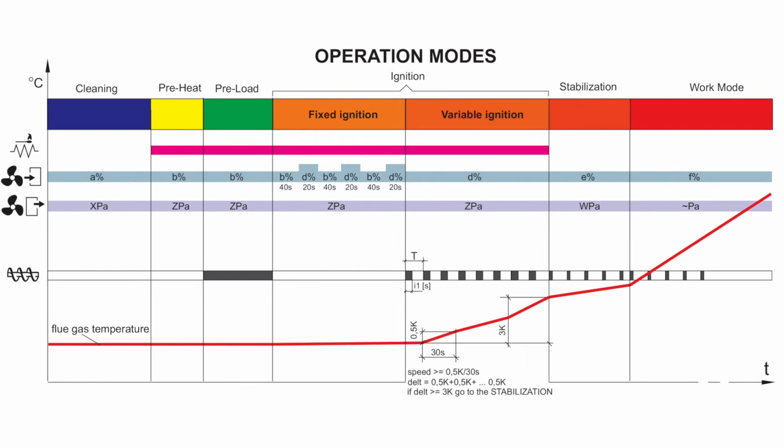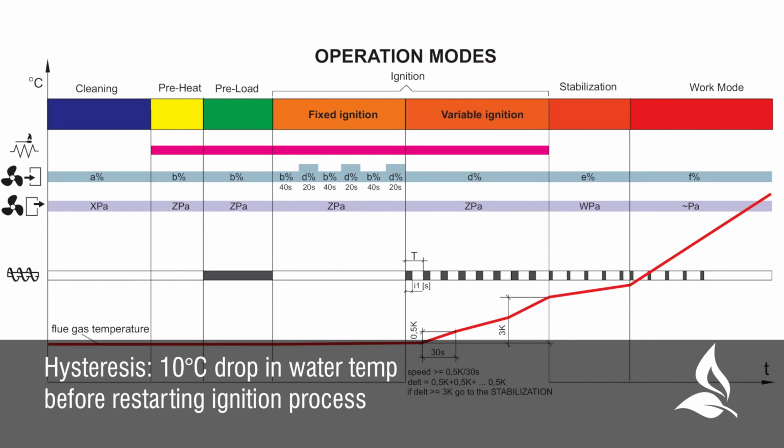The boiler operates on PID modulation, so will modulate freely between 30% and 100% of boiler output. Once it reaches the target temperature, it will continue to run at its lowest power for an extra 5 degrees Celsius temperature rise before going to the burning off extinguishing stage. Burning off lasts for a minimum of 7 minutes. Once burning off is finished, it enters final cleaning, which is compressor charging for 120 seconds and release of solenoid for 0.4 seconds. The boiler will remain in standby until the temperature drops by 10 degrees Celsius to restart the